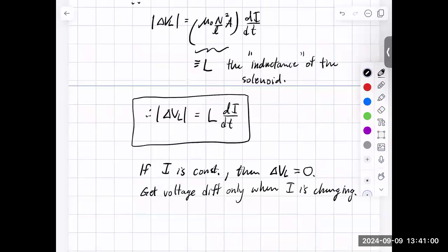Yeah, the voltage that comes out of here is sinusoidal. So it's oscillating all the time. If it's at 0 now, it'll go through a peak, come back through 0, go through a minimum. And so it's going from positive to negative through 0. So it's a sine wave. And what the 120 means is that's the RMS voltage. If you take your sine wave, you square it, you average it, you take the square root, that's 120 volts RMS. So we'll talk about RMS voltage probably in the first lab, actually.